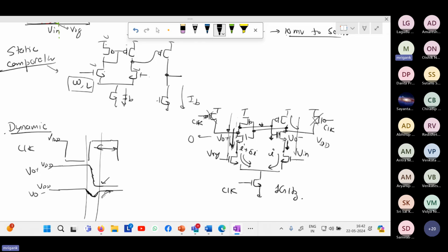provided you size it properly. So in this case, if you want to get a good operation, you need to have these two devices bigger because these are providing the conversion, the transconductance operation. The small signal current difference is generated by these two devices. So these two should be very well matched, and should be slightly bigger. These two devices are just for pre-charging. The output can be small. They don't matter much. The inverters also should be well matched and they can be moderate size. But the input devices have to be slightly bigger and bigger GM has to be there.